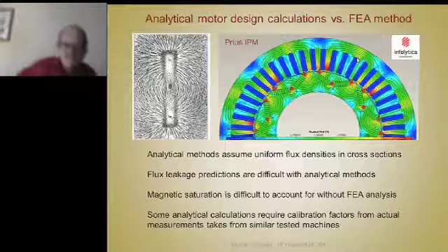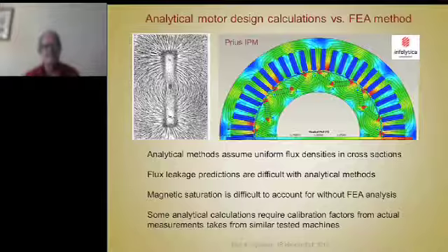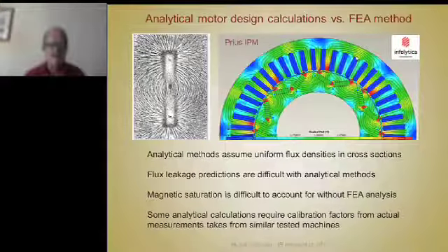In other words, the length of the path determines magnetic reluctance. A short path has lower reluctance than a long path, so the flux is going to tend to go around the shortest path. It doesn't want to go around the longest path because it takes more work, so to speak. To magnetize a short path takes less MMF than a long path. So there's going to be a gradient across here. It's going to be higher there than it is there.